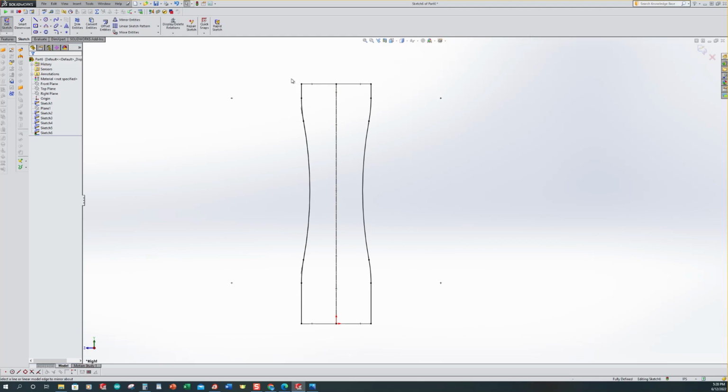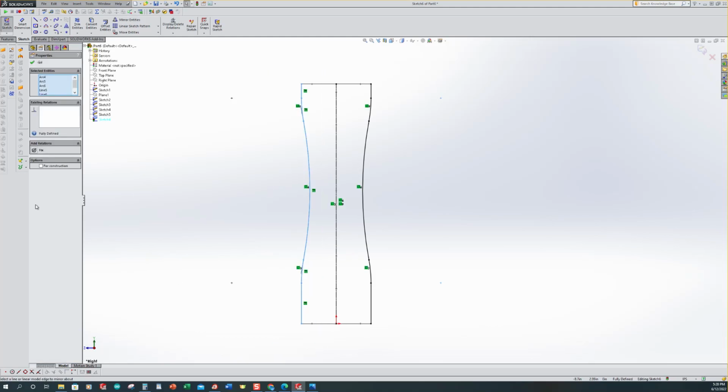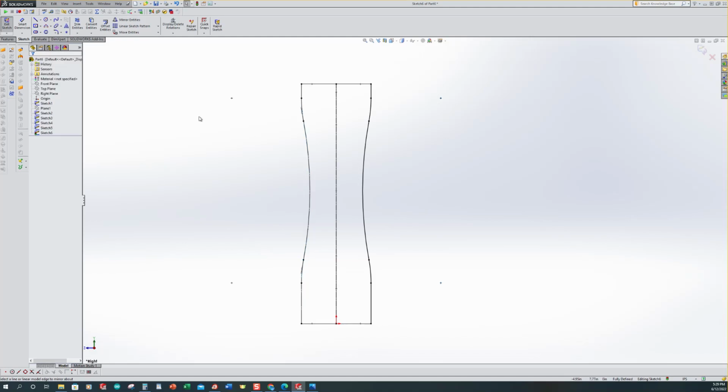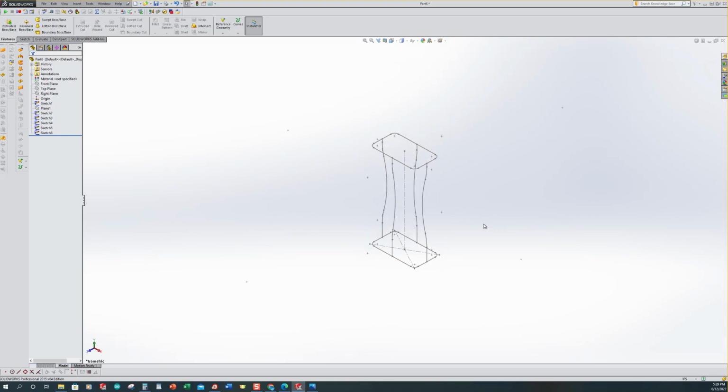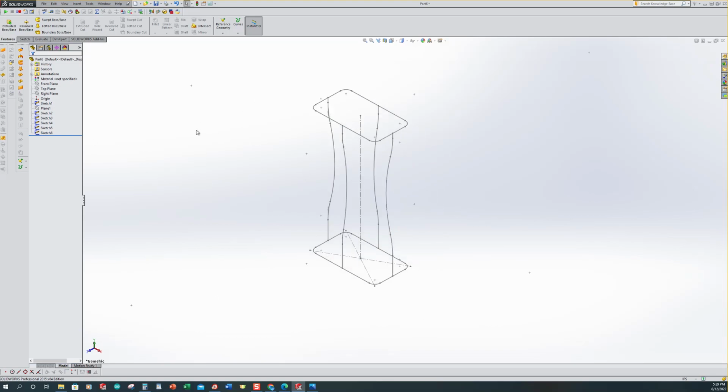Now this conversion is still a solid line, and we also have sketch 5 that is a solid sketch. So we want to make this side over here construction. So I'm going to draw a selection window around this side only, and I want to come over to the left hand side and change it to construction and accept it. So everyone use a Control 7 command. I'm still in the sketch, so I want to exit my sketch. I want to hit the escape key a couple times to make sure that I don't have any commands picked.